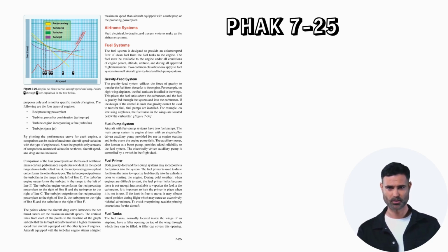It is important to lock the primer in place when it is not in use. If the knob is free to move, it may vibrate out of position during flight, which may cause an excessively rich fuel-air mixture. To avoid overpriming, read the priming instructions for the aircraft.